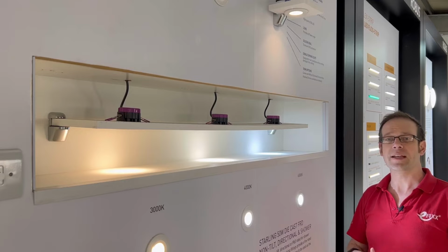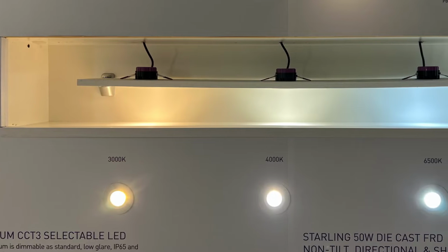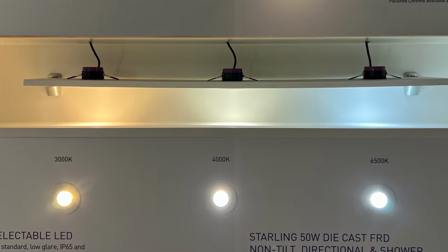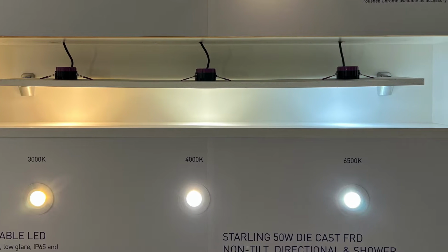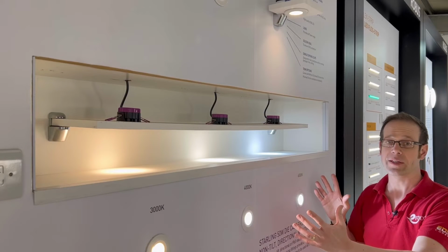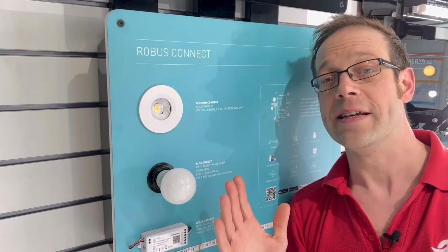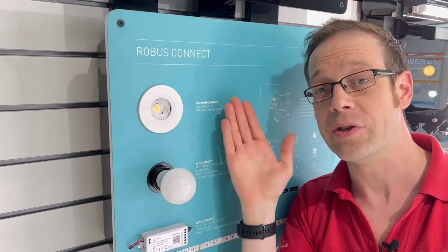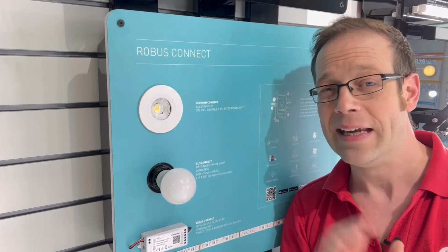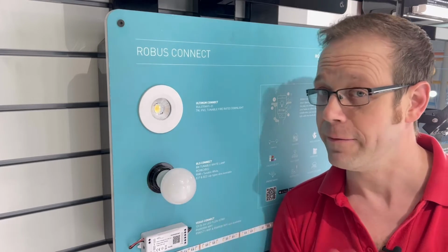Typical values for this range from very warm, which is about 2700 Kelvin, warm at about 3000 Kelvin. Colour temperature starts being classed as cool white at about 4000 Kelvin, then at about 6500 it becomes daylight white. Obviously values can vary between and outside these points, but these values have become a fairly reliable industry standard. Some light fittings like this Ultimum Connect downlight even allow you to tune your lighting to any point between 2700 and 6500 Kelvin if any of those discrete temperatures don't suit your needs, or if you want to use different values of temperature at different times.